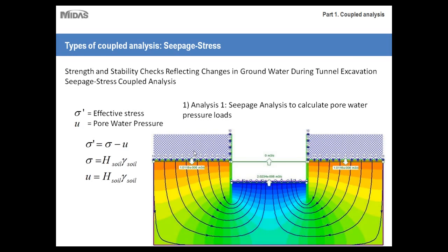well. So as you can see, just based on this image here, because the embankment or this tunnel lining has water on both sides, there's a large amount of seepage happening here. This would add increased pressure on these retaining walls as well as this floor of the embankment. First, the seepage analysis is done to analyze this flow.